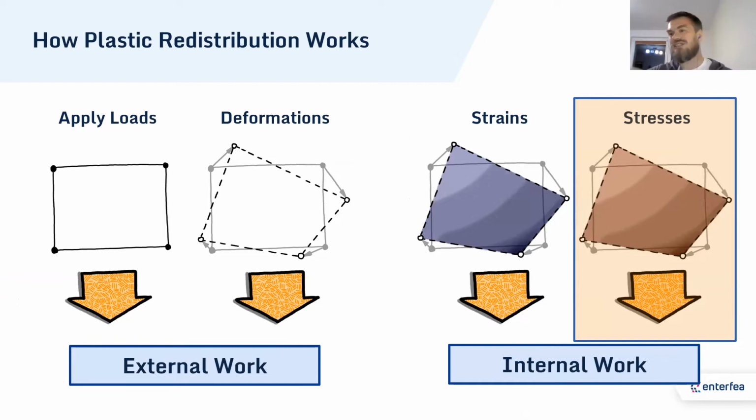Note that when we were discussing how the model behaves, if we wanted to check if it's in equilibrium, we took applied loads and deformations, calculated external work, and we took internal work and checked it, and they had to be in equilibrium. And now, after the solver solved your model, you want to ignore stresses. So that would put your model not in equilibrium, and it's risky.